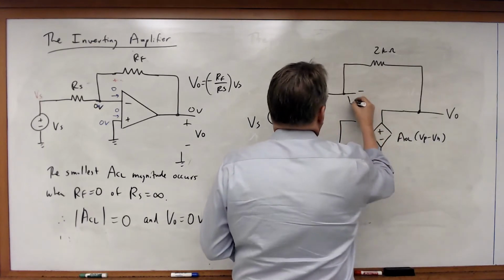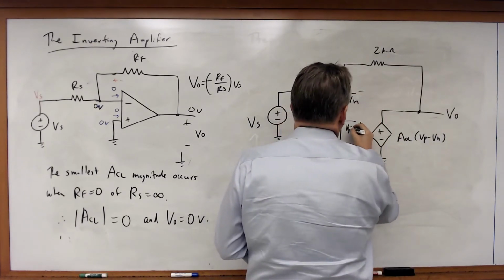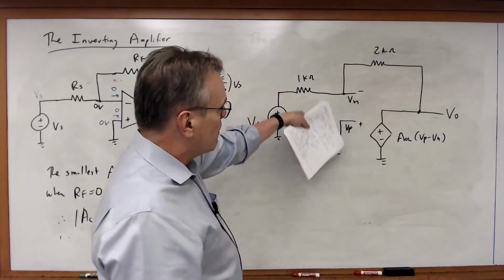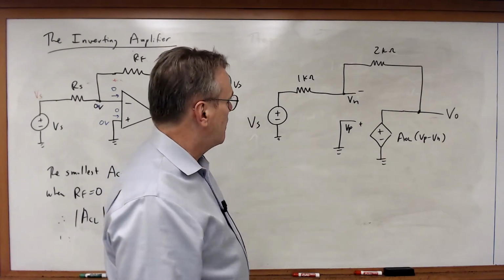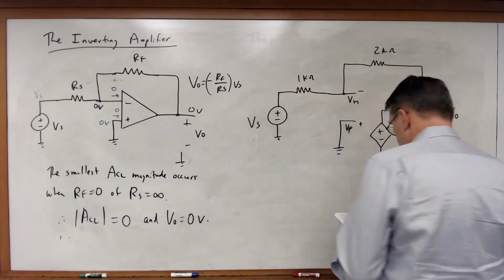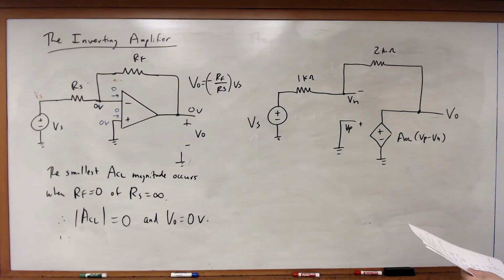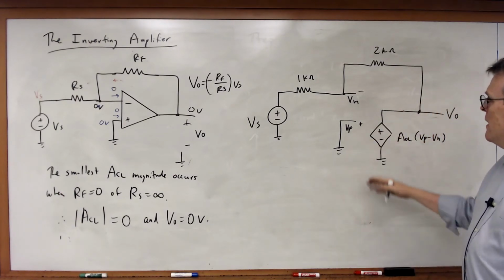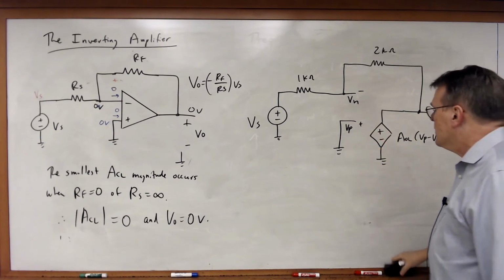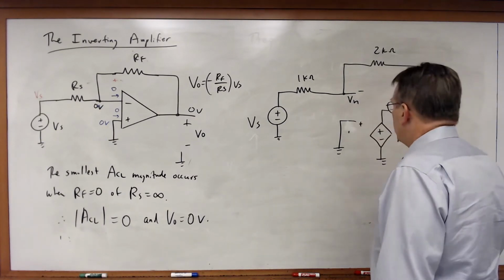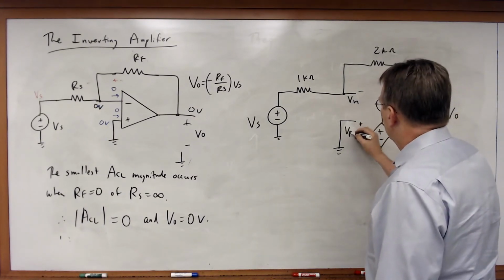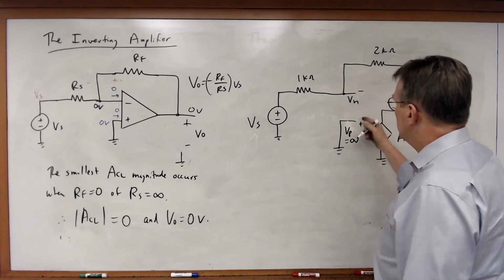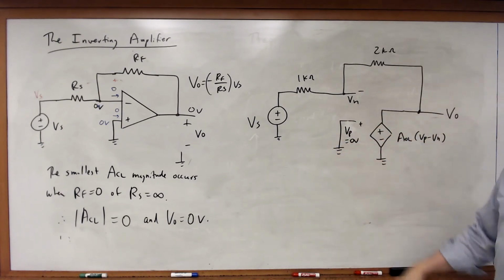So in this case, here's my VN, here's my VP for my inverting and non-inverting input voltages. And now let's go through and solve this. Okay, now once again, we're not going to make any assumptions about the 3 rules. So looking at this, clearly VP by inspection must be equal to 0 volts because, of course, the non-inverting input's connected to ground.